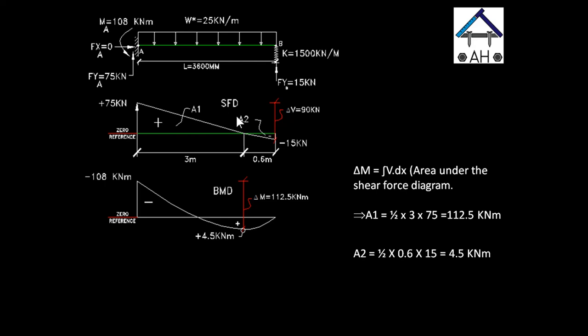Okay, some engineers make life a little easier by just adding the same reinforcements, top and bottom, for the maximum moment and maximum shear in the system. But you have to be careful here, because you don't want to have an over reinforced beam. Otherwise, you will get a non-ductile failure. When positioning the reinforcements, always check the neutral axis depth and ensure that you'll get the tensile steel to yield before the concrete crushes. In other words, you want to make sure that the steel fails before the neutral axis actually reaches up to the compression face of the beam.